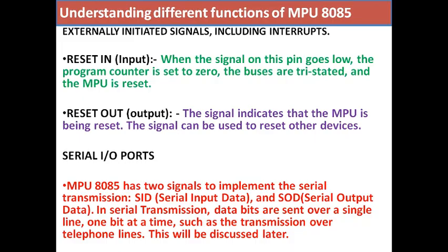Now a simple program counter, which is a register, is nothing but constructed out of flip-flops. Whenever you switch on a flip-flop for the first time, it is extremely difficult to predict its output.